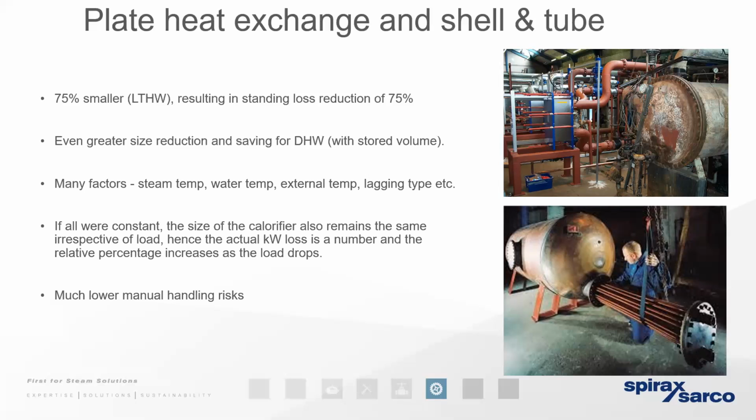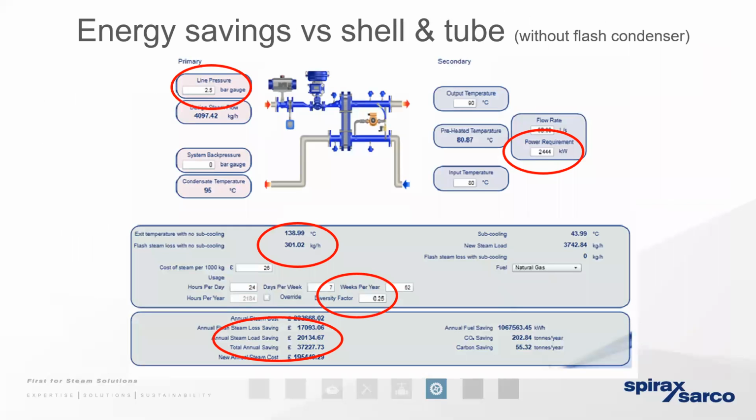So we've already mentioned how there's a benefit in ensuring that the heat exchanger is sized to condense the steam at the lowest possible pressure and at the lowest possible temperature. It means that, with more energy in the steam, the rate of heat transfer can take place very, very rapidly, but it also means it's going to take place far more efficiently. The reason being, that condensate that exists within the body of the heat exchanger is going to exist at the same pressure and at the same temperature as the steam.